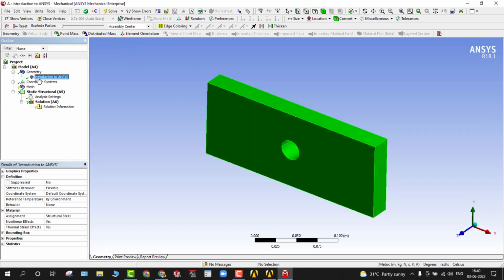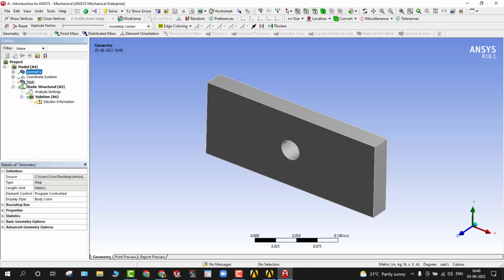In the model we have the geometry, and this is the solid model. So here you could see the material assigned. As I said, I had imported aluminum alloy as well. So if you want to assign it, you can assign it. If you want to change it, you can directly change it from here. You can even add multiple materials into your project to cross check the same. Okay, the material assignment is done. The meshing, there are different types of meshing available.